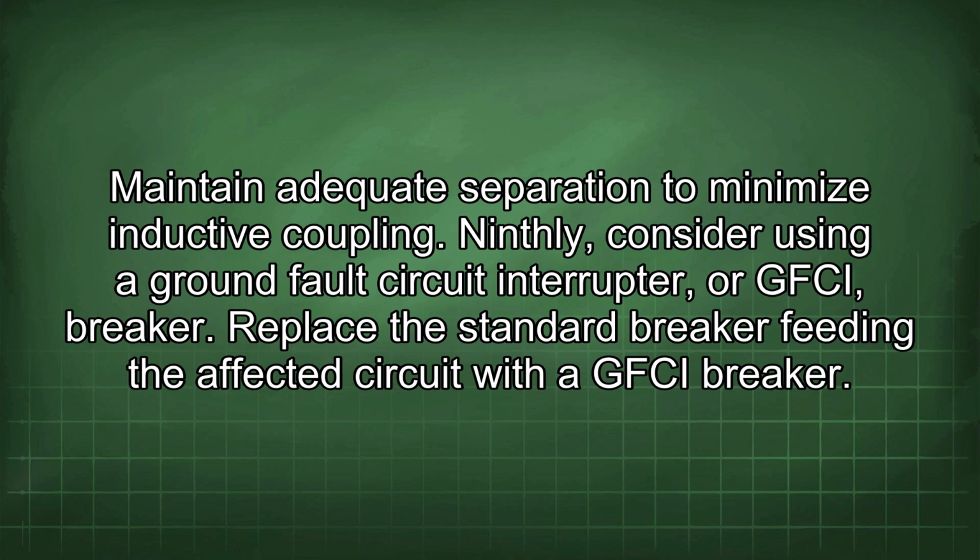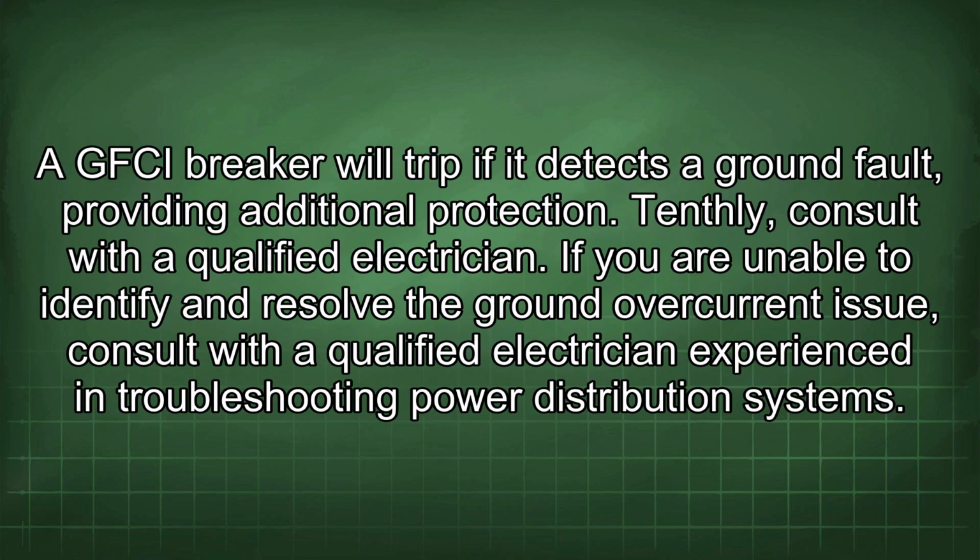Ninthly, consider using a ground fault circuit interrupter, or GFCI, breaker. Replace the standard breaker feeding the affected circuit with a GFCI breaker. A GFCI breaker will trip if it detects a ground fault, providing additional protection.